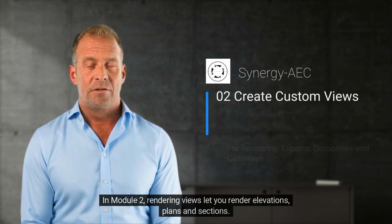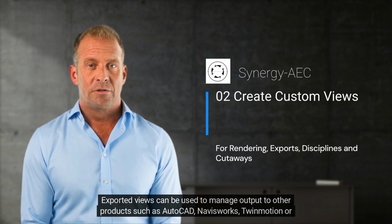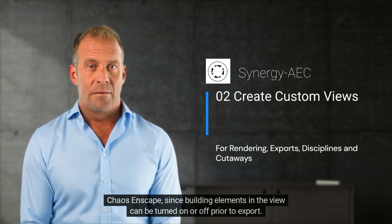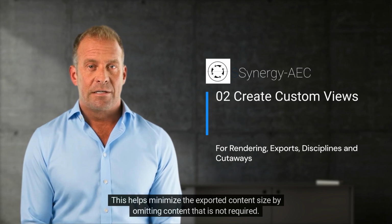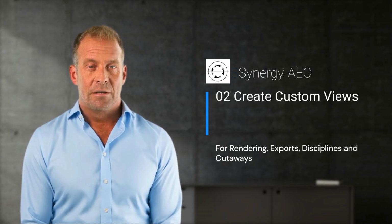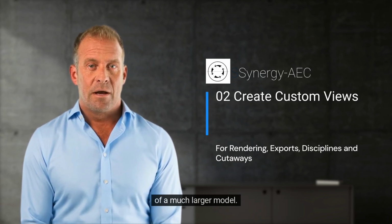In Module 2, rendering views let you render elevations, plans, and sections. Exported views can be used to manage output to other products such as AutoCAD, Navisworks, Twinmotion, or Chaos Enscape, since building elements in the view can be turned on or off prior to export. This helps minimize the exported content size by omitting content that is not required. Different disciplines may have different views in the one project. The BIM model can be viewed as cutaways, so the modeler can control multiple cutaway views as smaller portions of a much larger model.